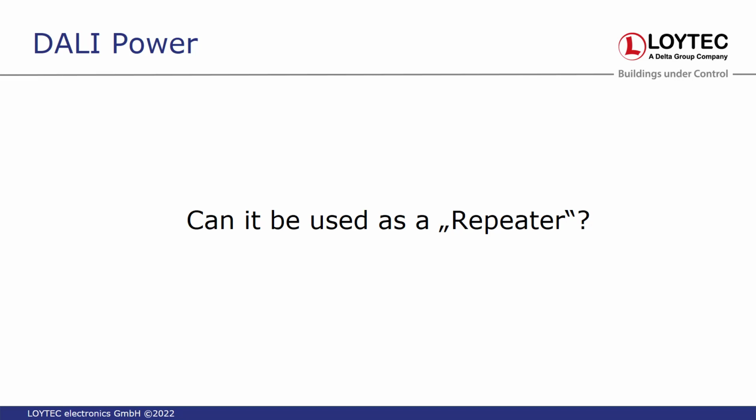I mean, the point is, no, this doesn't work, because this is not really a repeater. The DALI power supply is only supplying power, so it's not doing anything with the signal. The ballast and the controller make a short on the channel, and this is what it is.